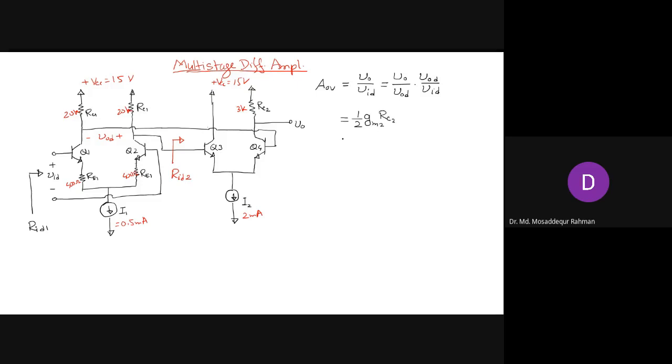That is the gain of the differential amplifier when we take the output from a single node. For the first stage, we are taking the output differentially, and also we have resistance in the emitter. When we have resistance in the emitter, the formula is the resistance in the collector divided by the resistance in the emitter. The resistance in the collector is RC1, and that is not the only resistance in the collector because the output is connected to the input of the second stage.